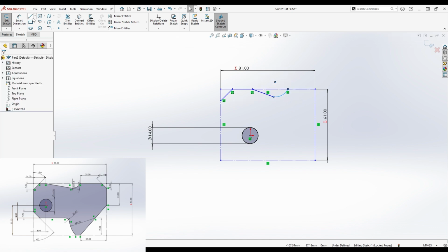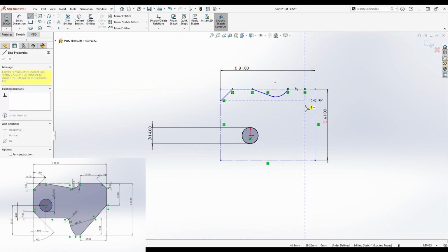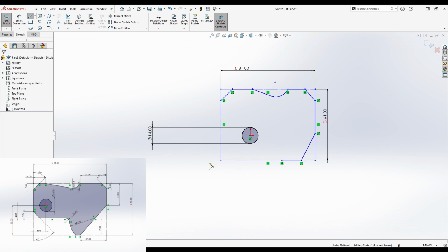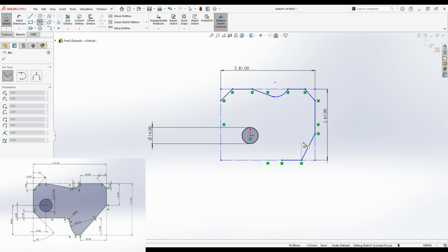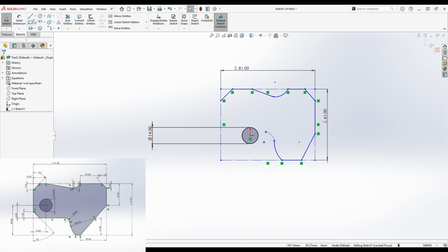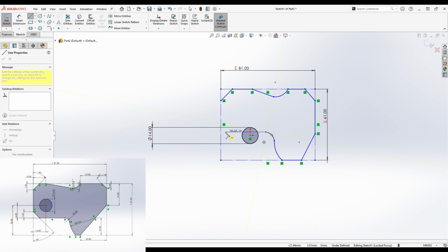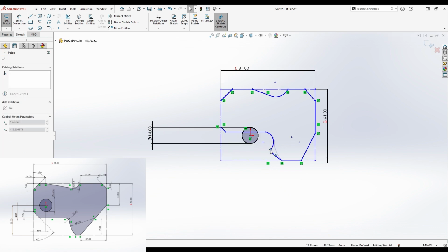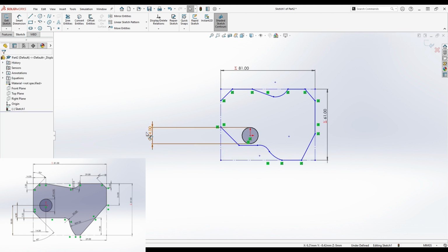We can change the center point, we can drag and drop it later on and continue with the rest of the lines and arcs. Again, an arbitrary point. I don't want to commit myself and say that the center point of this arc is going to lie in a line, although it is specific to this case. It might not look the same, but that's what we're going to do. Just going to drag and drop it. And then we could start dimensioning.